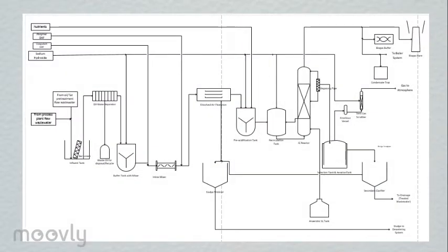For the process of wastewater treatment, a pretreatment process is needed. Wastewater from the production site will flow to an influent pit by gravity for collection to remove big solid particles and then will be pumped to an oil-water separator. The oil-water separator is used for free oil removal, and after oil removal the wastewater will flow into the buffer tank by gravity. The buffer tank is to equalize water quality and flow fluctuation.